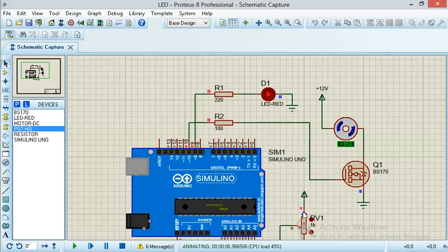You know, actually in real life too, an electric motor does not stop rotating immediately. Although there are advanced control systems where you can do what you want with an electric motor, there's a circuit called H bridge circuit. With an H bridge circuit, you can make a motor run in the forward direction, in the reverse direction, or in a brake mode. For example, let's say the motor was running and running, and you want to apply an instant brake, just like a real car brake. You can do it with an H-bridge circuit such that the electric motor will come to a halt immediately.